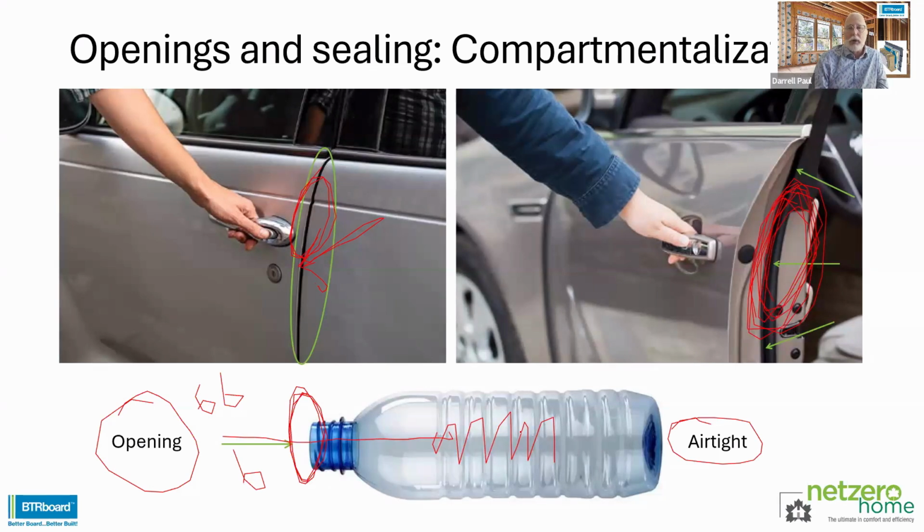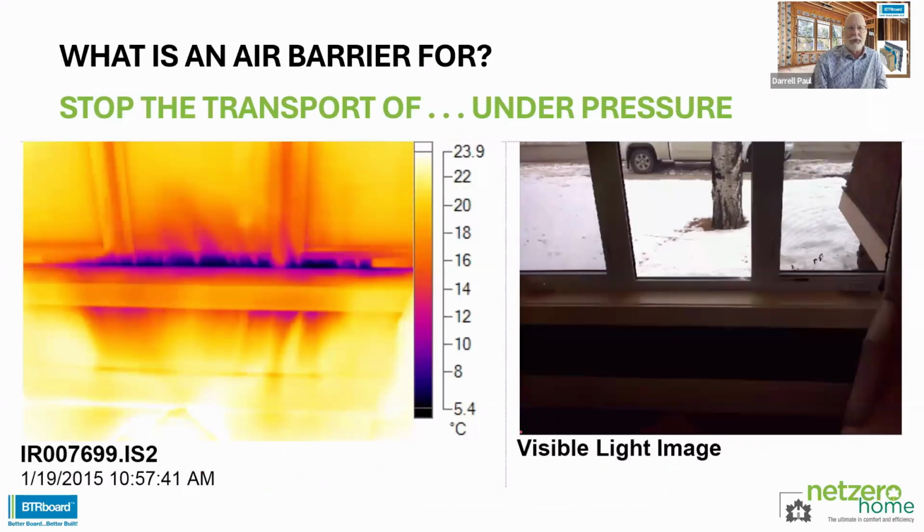So you're really blocking and preventing air from getting in there by means of a pressure equalization system, which is similar to what we use in a rain screen or a drained and vented airspace. It's the same principle. So now, if we take that principle and apply it to something like a window, and we look at this window here, this is a window under air pressure, so we've got a blower door going. But you notice there that where they've attached the jamb extension to the window, there's a significant amount of air being drawn in, and at the casing underneath, there's additionally a significant amount.